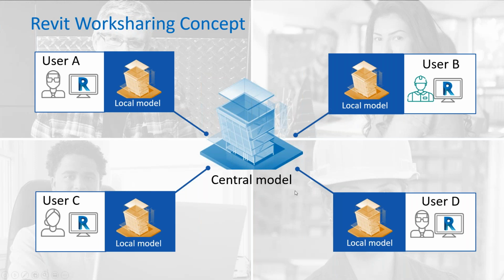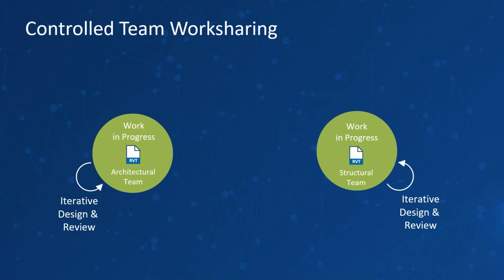Which is the first step to making it easy for people to use it, because if you've heard of the work sharing concept in the past, work sets, save to central, reload latest, relinquishing objects, etc., well, basically that's the same in BIM 360 Design. There's a couple more functionalities in there, which address what you see in this slide.